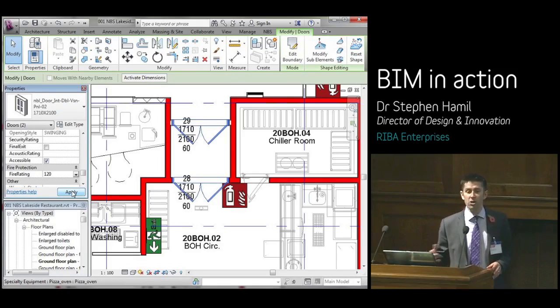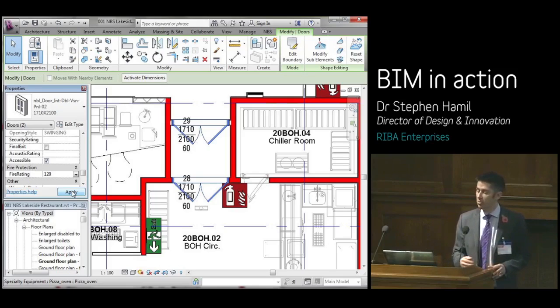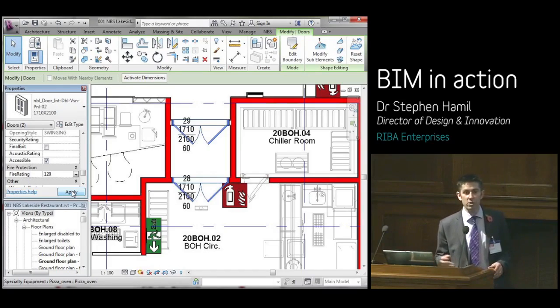And there's a little bit of color coding here on the analysis to say everything that's 2 hour fire rating turn red, everything that's 1 hour fire rating turn blue. And if you think of the UK regulations around a kitchen space, approved documents for fire safety, it's a 2 hour, so a commercial kitchen, 2 hours fire safety for all the elements. So you can quickly see that those doors, those internal double swing doors, haven't got the correct fire ratings.